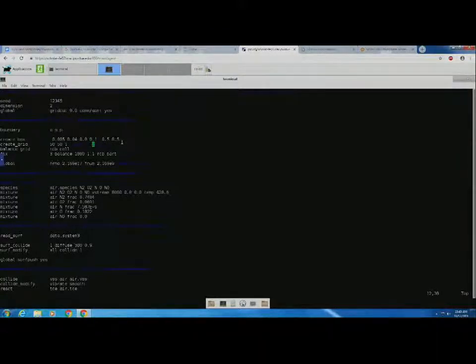Create grid. If you remember in DSMC, you discretize the domain into cells, so that's what we're doing here. We're saying that I have 50 cells in the x and y, and just one cell in the z, which again is required for a 2D problem.